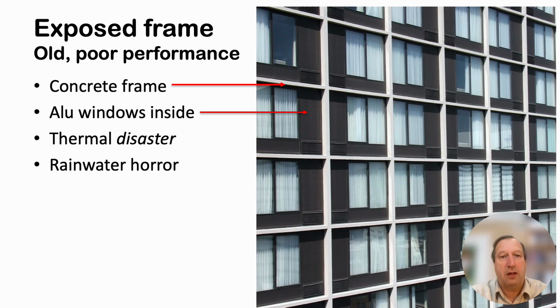This is a hotel. There's a solid floor slab, shear walls between each of the apartment units, and it made this grid work into which they inserted this aluminum tube support structure, where they filled in some of the panels with metal and HVAC grills and some of them with glass.